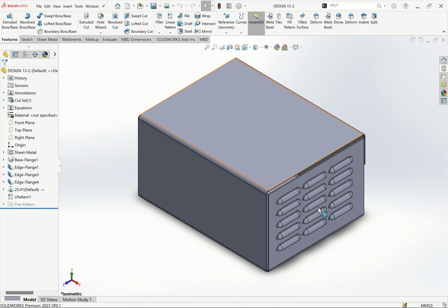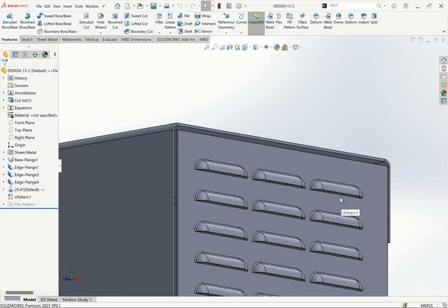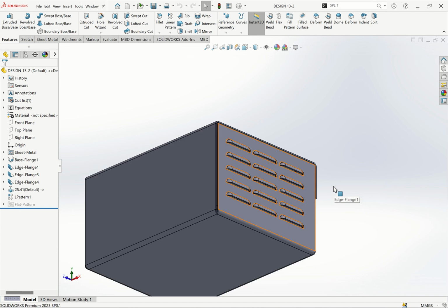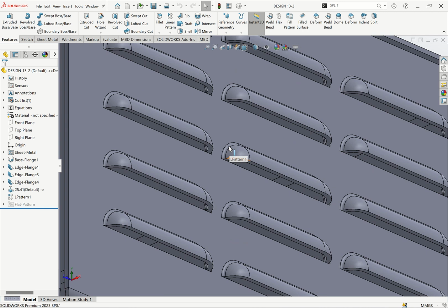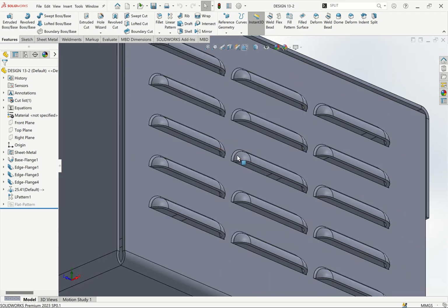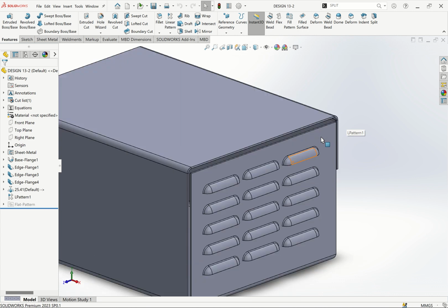Well, for the purpose of ventilation, if you have a sheet metal part, you want to do a ventilation feature on your model. I used it in most cases in heavy equipment where maybe it has movers or motors that would require ventilation, and at the same time need to prevent dust from entering the system. That's why you require these louvers.